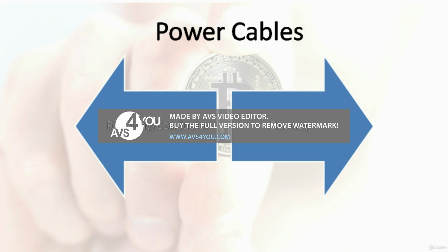As briefly mentioned in the other videos, how power cabling works really depends on your region's electric code. So what I'm going to talk about is going to be very generic. For example, in the United States, we will refer to NFPA 70 and NEC Article 300 and 310 for wiring methods of the mining farm. As general methods, we usually have two choices: the raceway conductor method and the busway method.